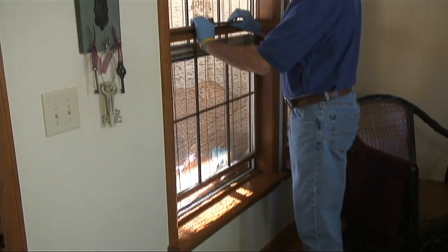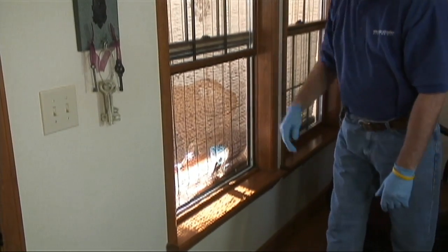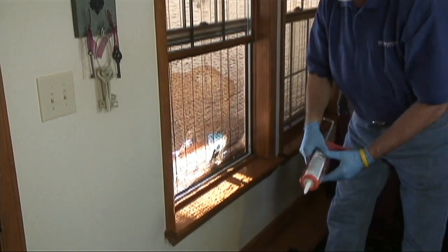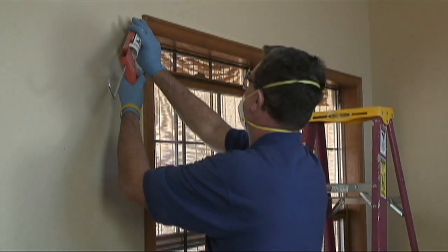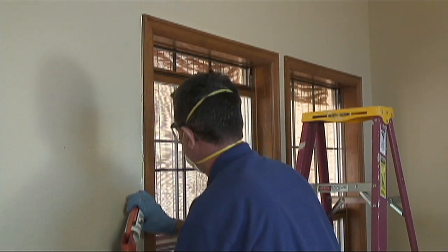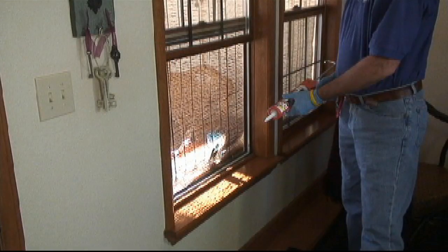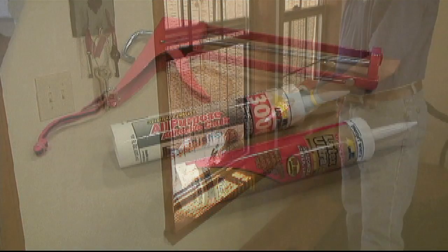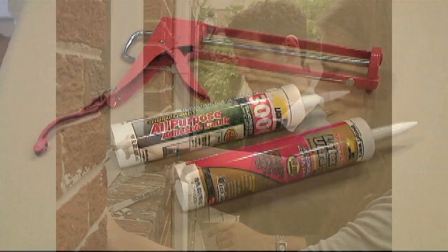As you begin your air sealing and caulking project, you should take all normal, necessary safety precautions and use good safety practices. You should always wear a respirator or dust mask, safety glasses or goggles, old clothes, and nitrile gloves as you are installing caulk. It is best if the area of the house in which you are working is well ventilated. We recommend using a low-odor caulk on the interior of homes, as there may be a small residual odor for 24 to 48 hours after caulking.